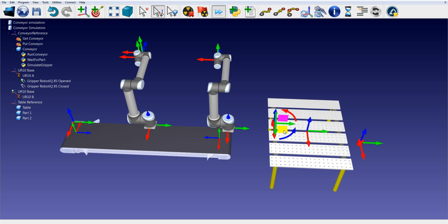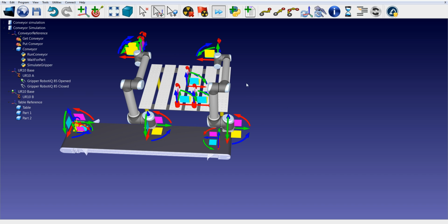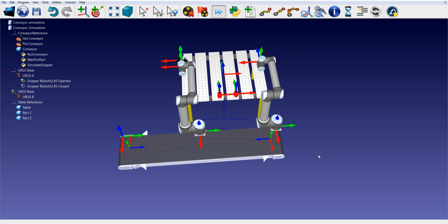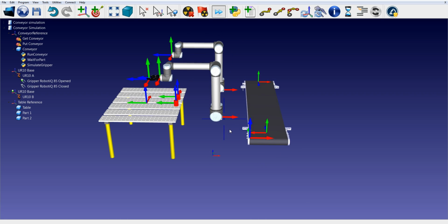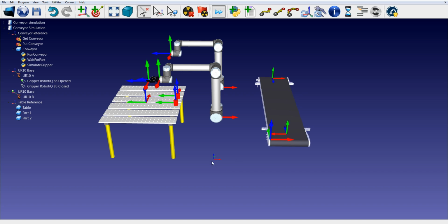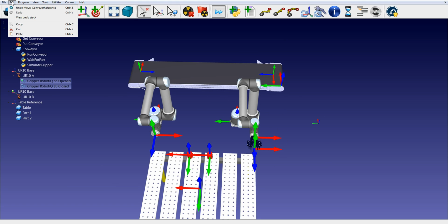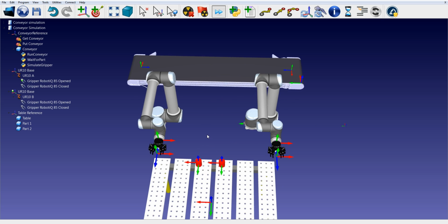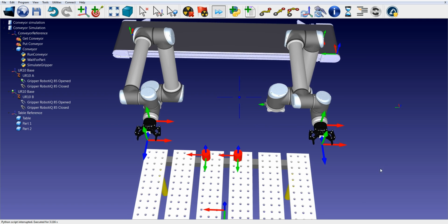We can use the Alt key again to move the objects with respect to each other. We can also copy-paste the 2 grippers from one robot to the other. We can easily run the program Simulate Gripper. This will automatically hide the tools with the closed tag that are not grabbing anything.